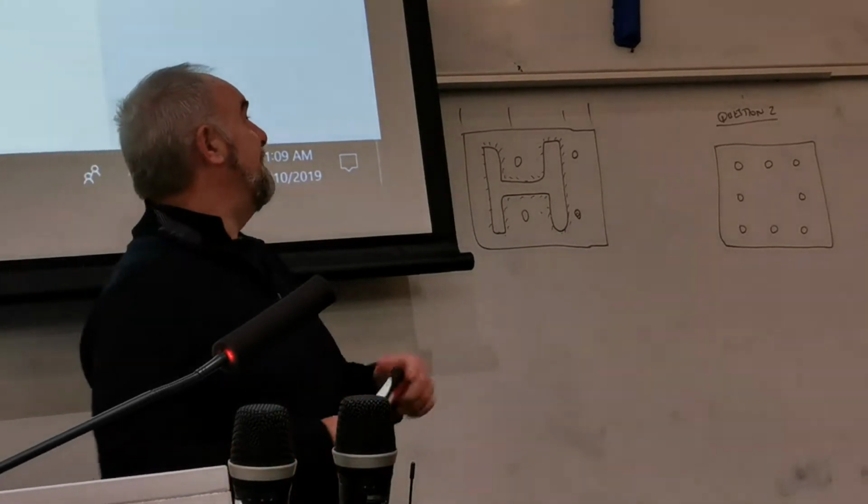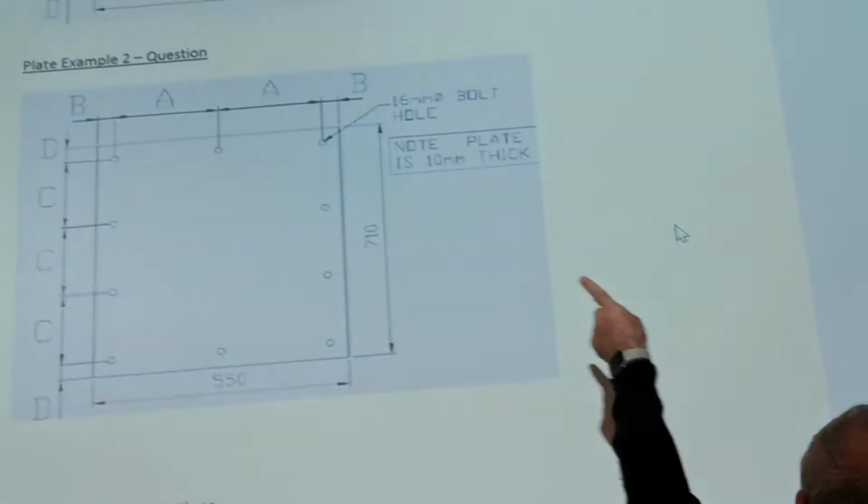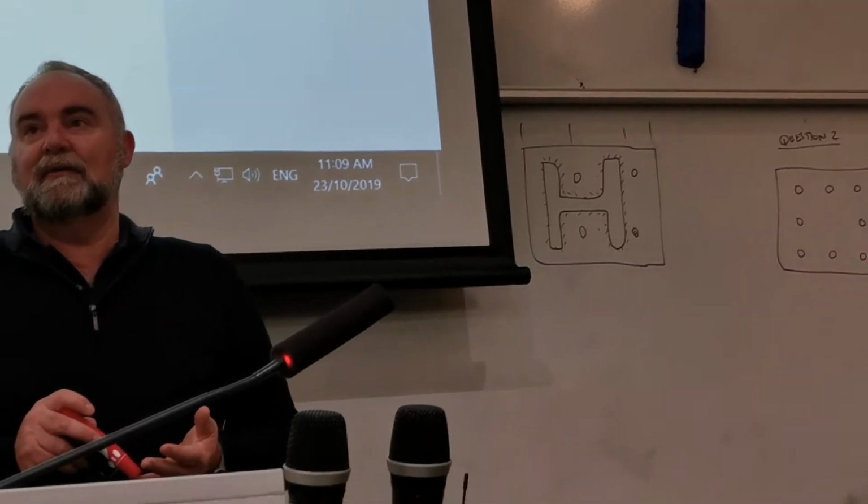You might think I'm fussy for things like that leader, which is again wrong up the top. But there are other things that industry doesn't tolerate. For example, getting your dimension settings wrong, getting your text heights wrong, and putting leaders through dimensions.